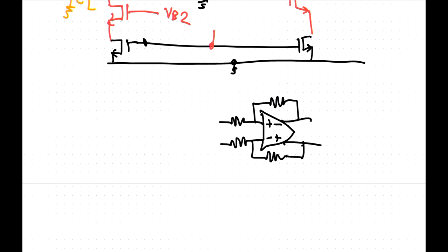It's got to be completely symmetrical. So you look at the difference at the output and you feed back that difference to the difference of the input. It doesn't say anything about what the actual voltage is. So both at the input and the output we have the common mode and a differential. The feedback is in the differential. The common mode can be anything.